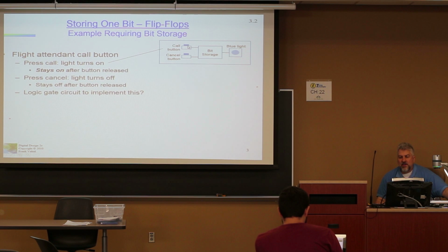Now you notice, this is not changing the input. This is actually an input that says when you press the button, it will go from 0 to 1 for a certain amount of time. And then based on that, this will stay on. And it will stay on until you get the push of this button, which will be going from 0 to 1 and then back to 0.